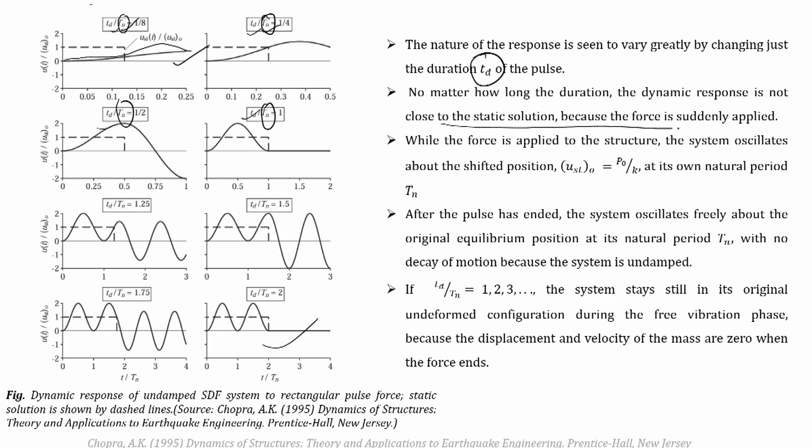Whatever happens, the maximum response will never be close to the static solution, because the force has been applied suddenly. So the dynamic solution will always vary from the static solution. When the force is applied to the structure, the system oscillates about the shifted position. So the system is oscillating with respect to the static deflection position, at its own natural period.